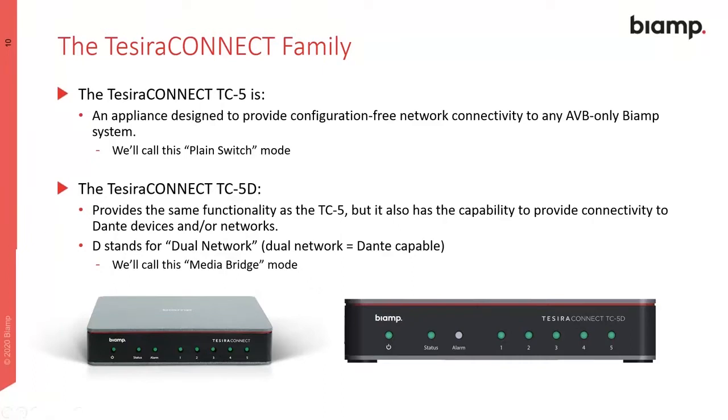So if you have a Dante input, you want to connect it to an AVB network, you can do that, and the vice versa is acceptable as well. So if you have an AVB network and you have a Dante server from Biamp, then you can bridge from AVB back to Dante. So let's say you have a Tesira Forte DAN, for instance, and you have an AVB amplifier. You want to use our PoE AVB amplifier. Through the Tesira DAN, you can bridge the AVB protocol into the Dante network as well. And we will see some exercises on how to do that.